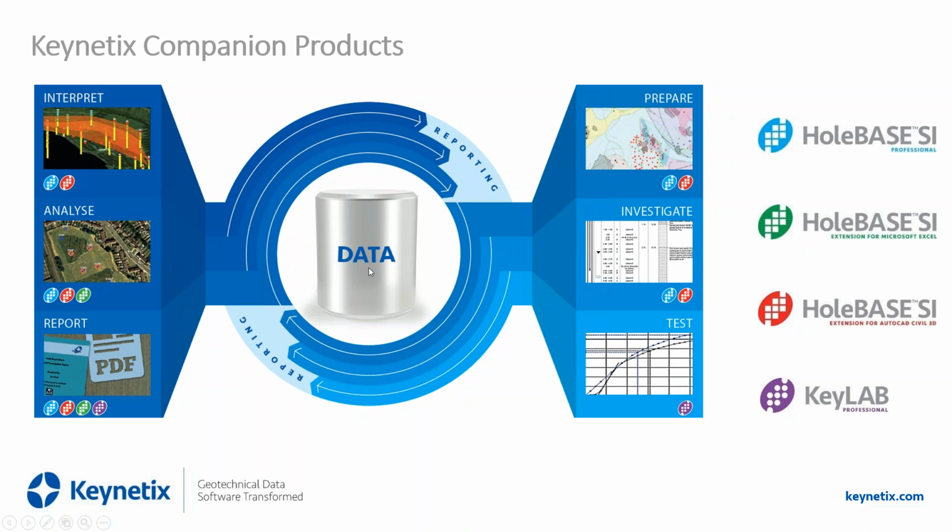Now, if you've got all those results in your central database, and we're connecting through to it from AutoCAD Civil or from Excel, we can show that data as well. So all the lab results, the stiffness of the ground, Californian bearing ratios, water content, we can actually exploit that data and show it and visualize it inside AutoCAD Civil or inside Excel. And that's really what our range of products are all based to do. It's basically working on geotechnical data and allowing you to look at it, visualize it, and use it to better understand what's going on in your site and do better engineering.